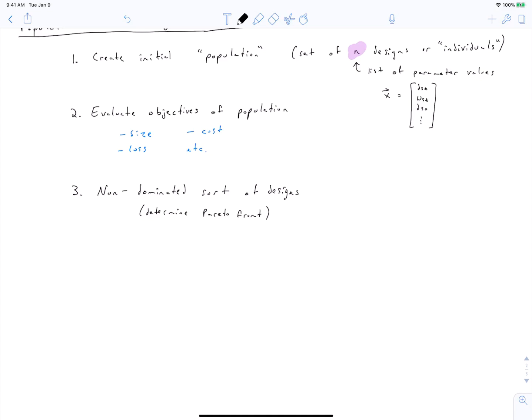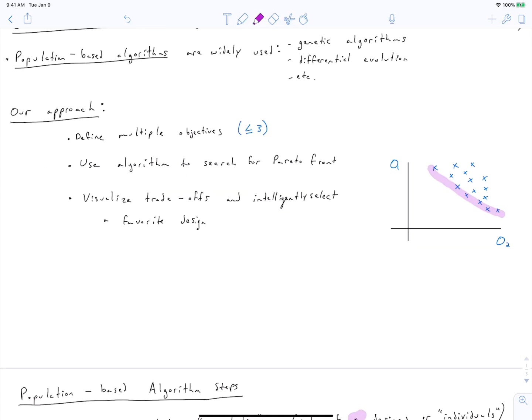So your Pareto front is constantly moving. Your design space has a true Pareto front. You just don't know it. You haven't evaluated enough designs to find out where your true Pareto front is. And so the first time you evaluate a set of designs, you figure out which designs do not dominate each other, and that becomes your Pareto front. Now you have some information, so you intelligently create a new set of designs. And when you evaluate those designs, then you discover that, oh, my Pareto front is actually closer over here.